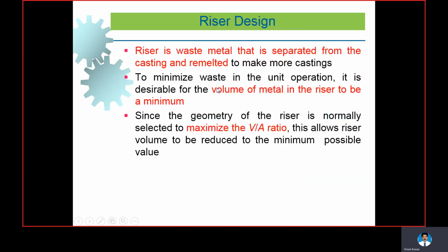So riser design is a very important factor because the riser acts as a reservoir to supply molten metal continuously to the cavity. Hence, riser design is very important, and we have to keep the volume divided by area ratio more than the casting for a riser. So for a riser, V over A, volume to area ratio, must be more than for a casting.